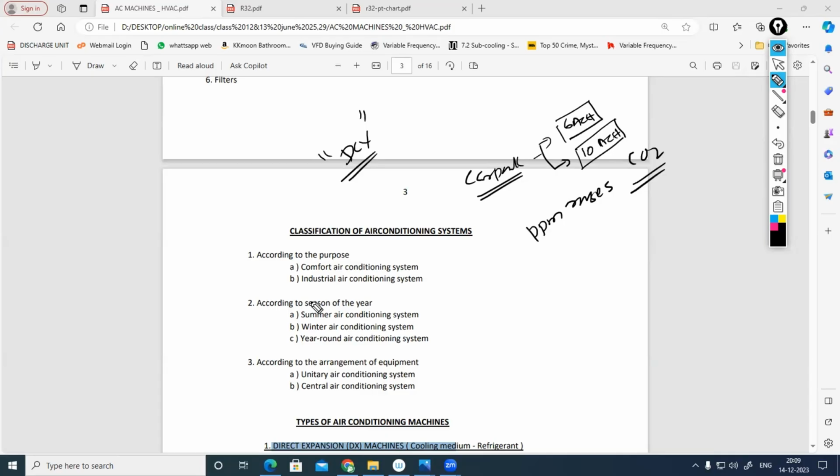At that time, I will explain this one. Demand control ventilation means whenever it is in demand, at that time only, your ventilation equipment will start. Exhaust fan, how will it work? Normally, in the car park exhaust system, the exhaust fan will be off.